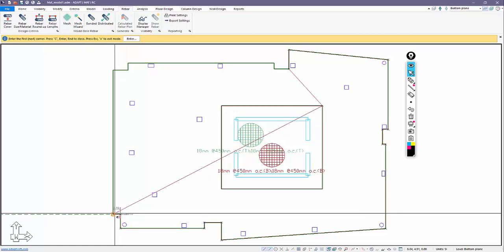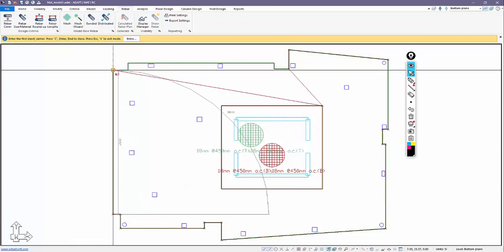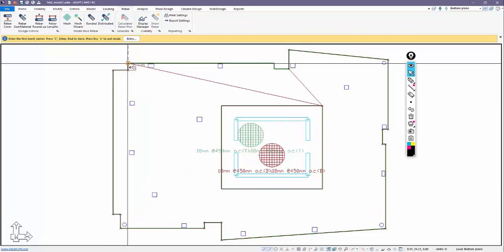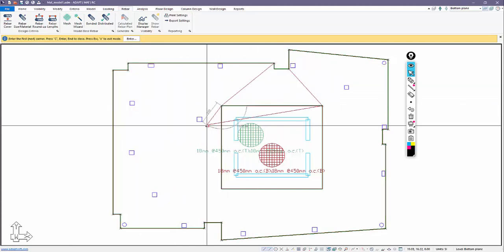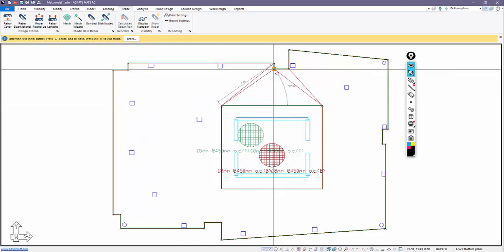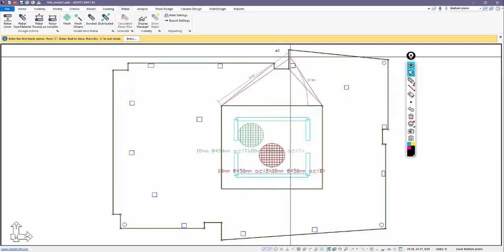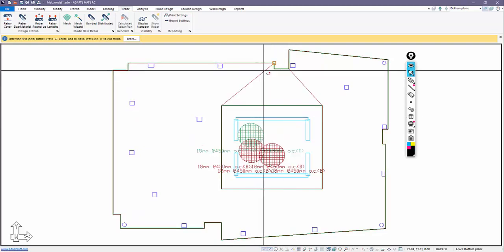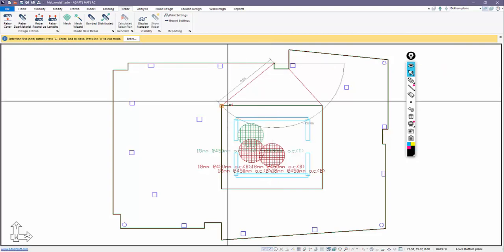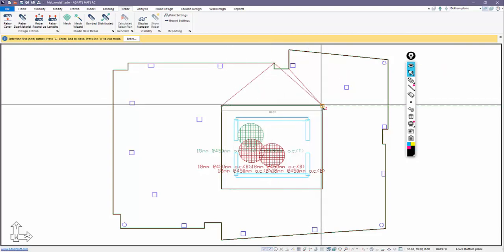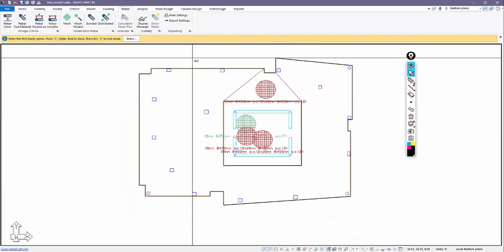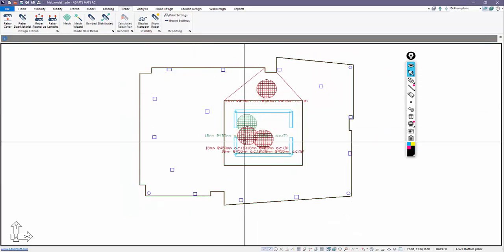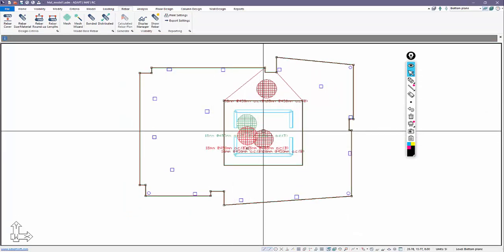Okay, so we'll select this zone here, and I'll actually come over there and click that. I cannot have 2 points touching on the same polygon, so I have to create this third region. We'll press enter, and then the third region will be something that looks like this. There's the third region. Okay, and now if I select these different regions, let's select this one here.